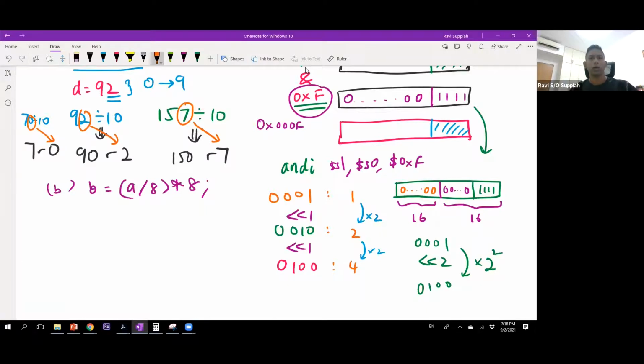This is in the case of, let's say, an odd number. And again, why is this very important? Because you want to optimize the final assembly language code to run as efficiently as you can. Even though your processor may support multiplication and division operations, they are considered very computationally intensive because they take a lot of clock cycles to complete, whereas if I can replace those instructions with shift operations, they are a far more efficient way of achieving the same outcome.